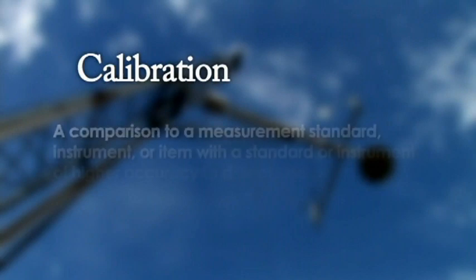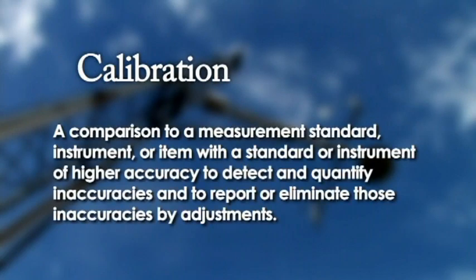Before we get going, let's define what we mean by a calibration. EPA defines a calibration as a comparison to a measurement standard, instrument or item with a standard or instrument of higher accuracy to detect and quantify inaccuracies and to report or eliminate those inaccuracies by adjustments. So you can see there are two parts to this process. Primarily, the measuring of conformance, and secondly, adjusting to that conformance. What this translates to is testing and adjusting the instrument to see if it meets our standards.